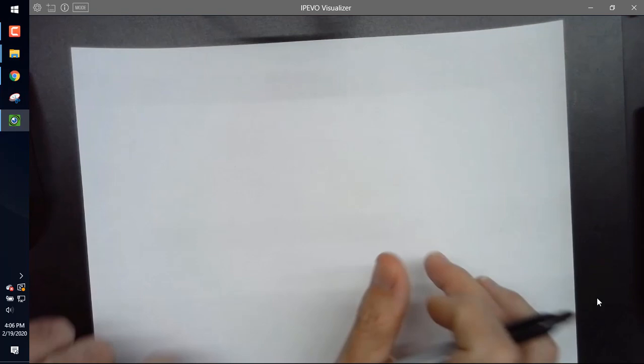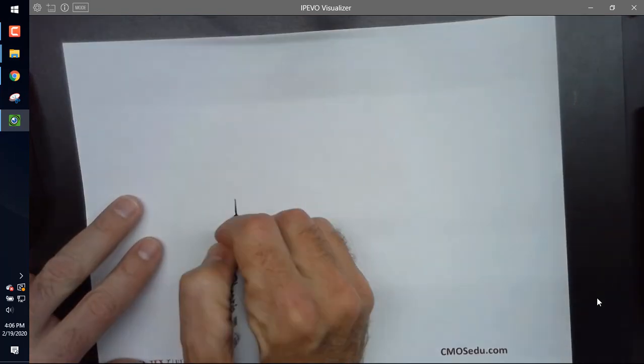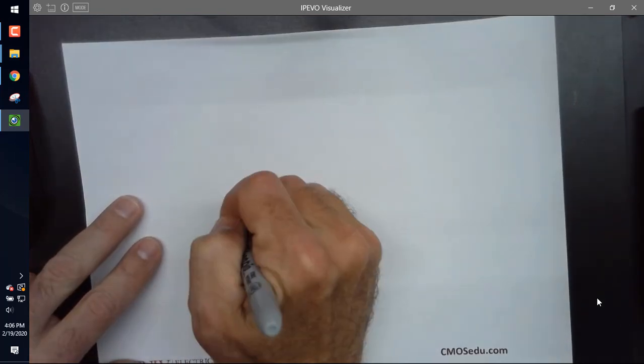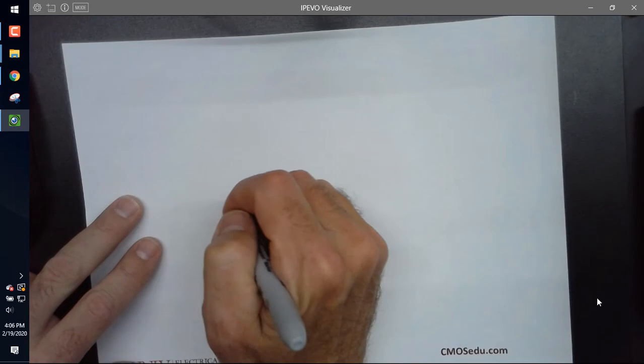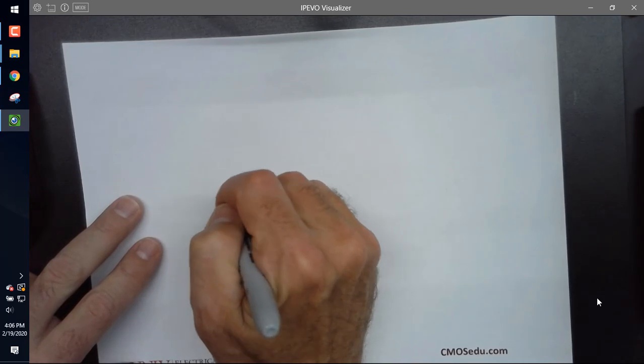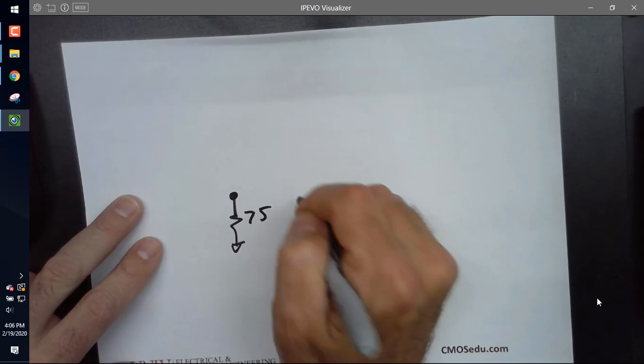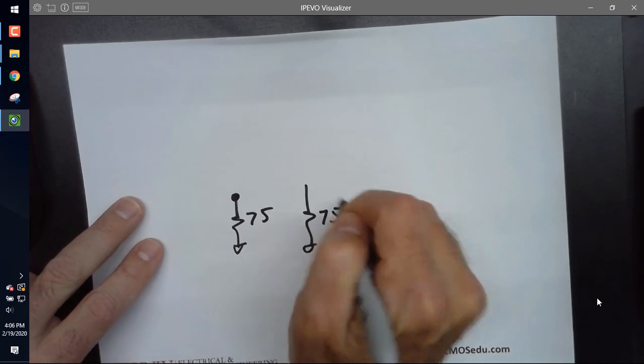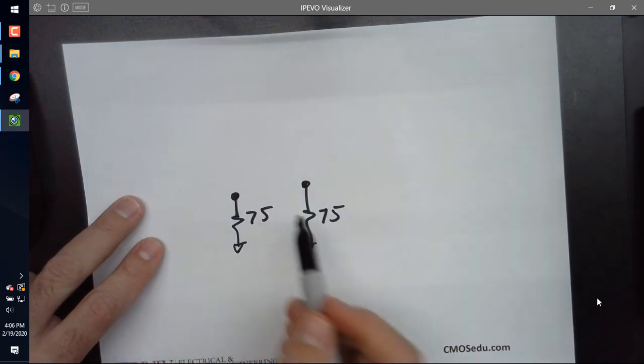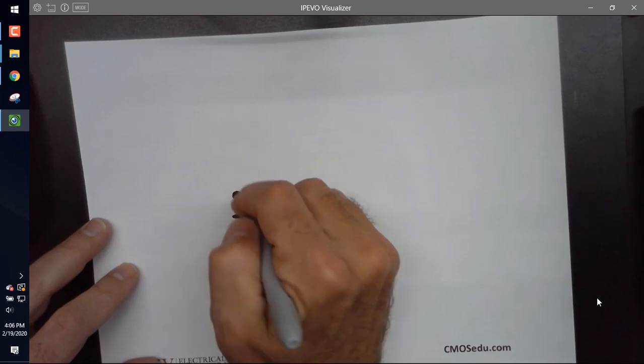If I look at the input to the monitor, it's a lot more complicated nowadays, but you might have 75 ohms and 75 ohms, the two loads you have to drive in the monitor. You measure the impedance and get 75 ohms, and you get a plus node and a minus node.